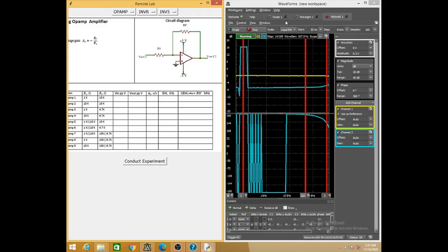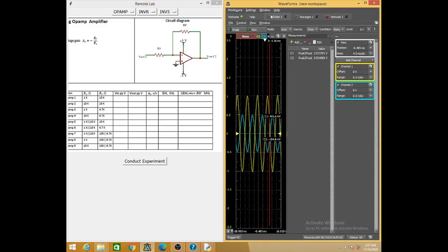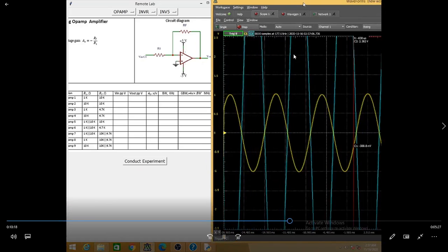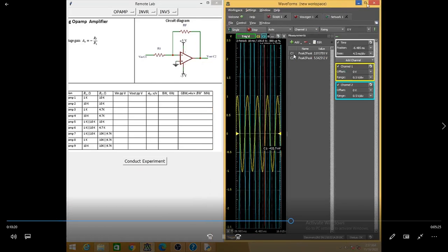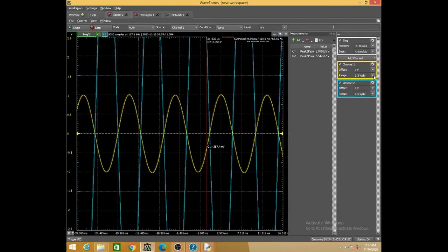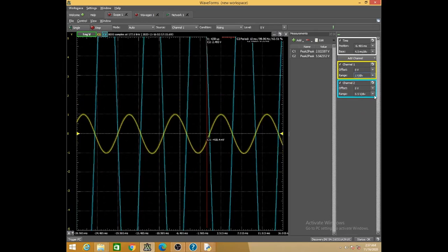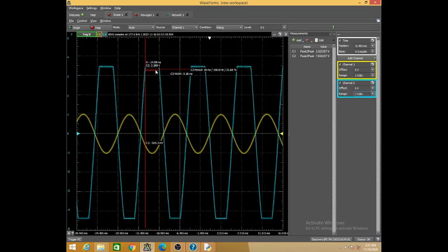Now it is INV5. INV5, can you see the gain has gone up? Now gain is too much? You can see it is going above the scale. Now I have to change the range, volt per division. These are the simpler modifications you have to make. Can you see now it is clipped off?